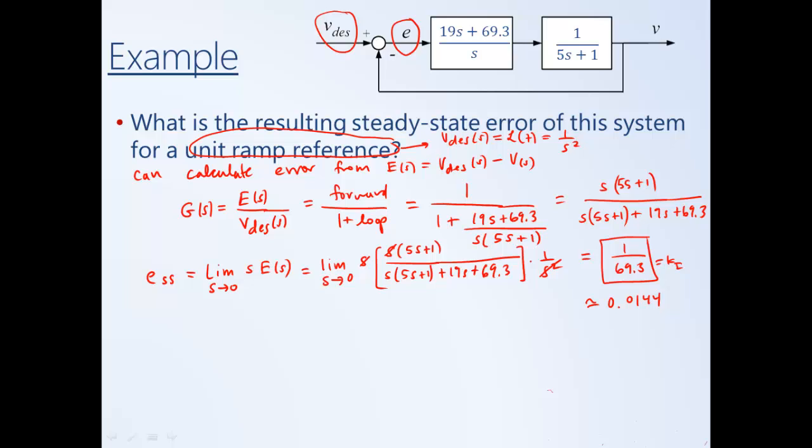The proportional gain doesn't appear to affect the steady state error at all. If we had a condition on steady state error that conflicted with the condition on the peak time or the settling time, we may have to iterate in the design of our controller, pushing back and forth between the various requirements.